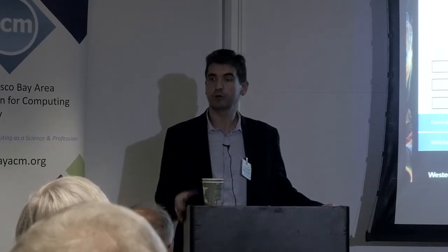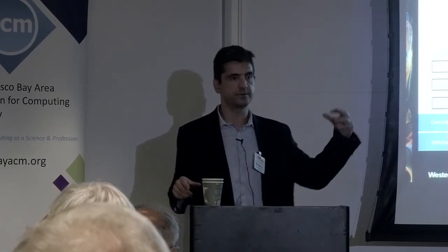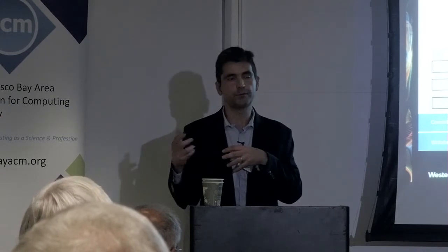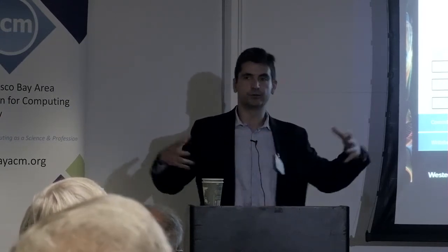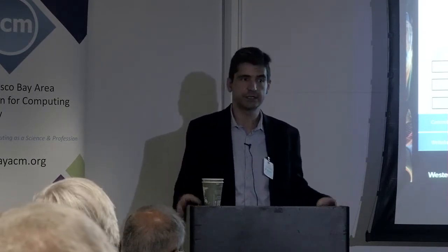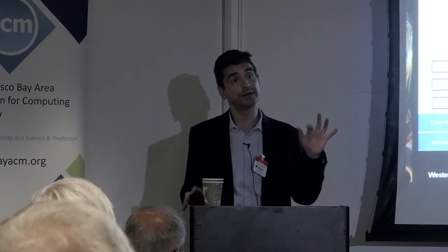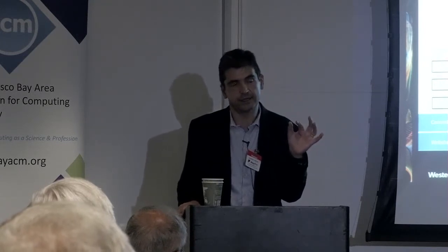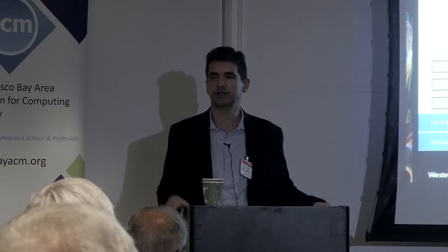What you can do is add more stages in the pipeline. When you break the compute process into fetching, decoding, doing useful things, and committing back to memory or to the register file, you can do this in one step, like a one-cycle core, or in 5, like in the classical pipeline, which makes sense, or go more. And when you have a larger number of steps that take a smaller amount of time, the consequence is that you can run at a higher frequency. So that's a nice thing. You get some acceleration from that.